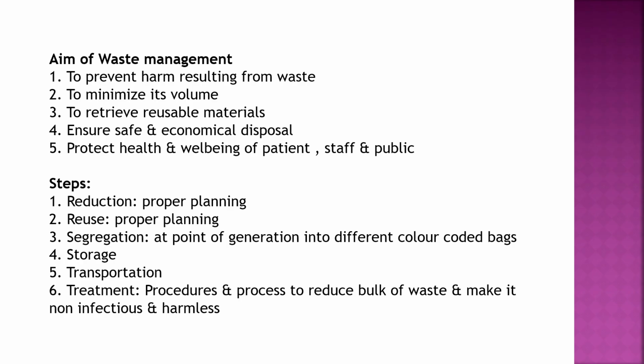So first is the reduction. So proper planning so that the waste volume should not increase. So the main first step is the reduction of the biomedical waste. Then after that, whatever waste is generated, you have to recover that. So reuse. So proper planning of the reuse of the waste produced. Then segregation. So at the point of generation, the waste should be segregated into different color coded bags.